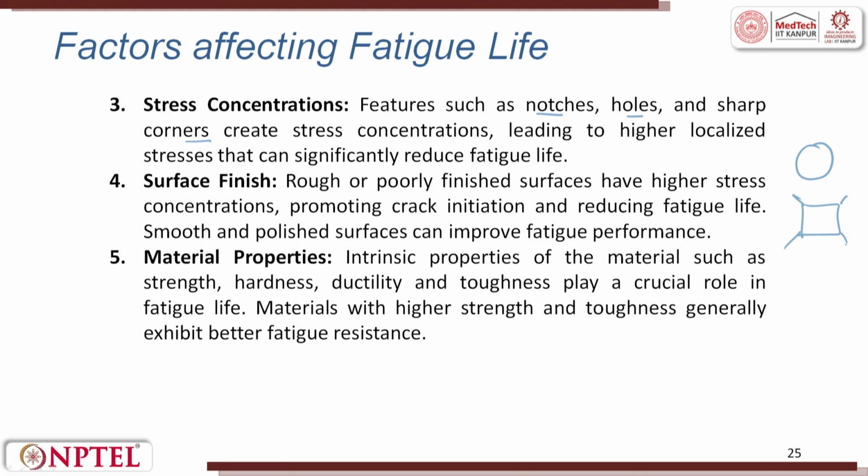Surface finish. Rough or poorly finished surfaces have higher stress concentrations, promoting crack initiation and reducing fatigue life. Smooth and polished surfaces can improve fatigue performance. Material properties. Intrinsic properties of the material such as strength, hardness, ductility, and toughness play a crucial role in fatigue life. Materials with higher strength and toughness generally exhibit better fatigue resistance. So, toughness is the area under the curve, you remember the stress strain graph.